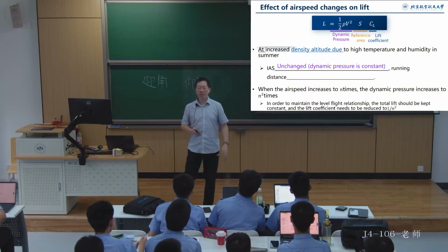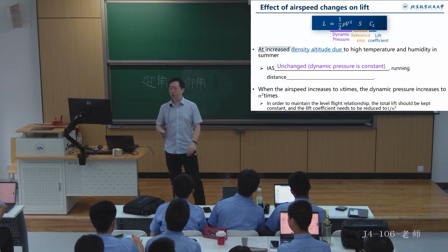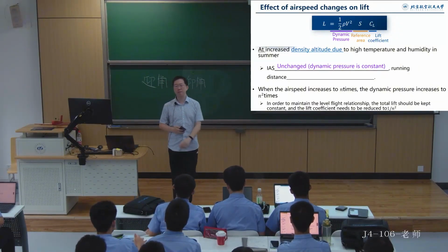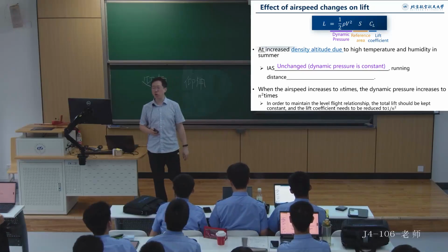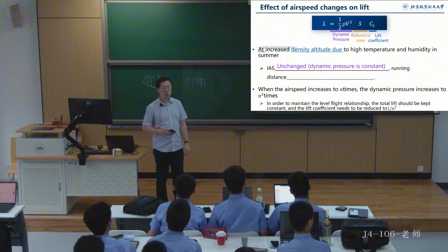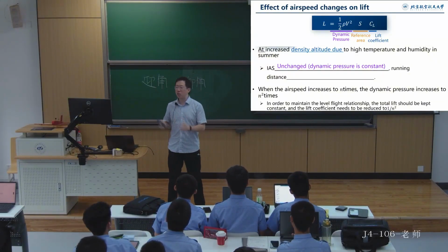The speed we accelerate to relative to the ground should be ground speed. But what I want to talk about is airspeed, because I've already assumed a no wind condition. The speed I should accelerate to relative to the ground should be the same as the true airspeed, right?